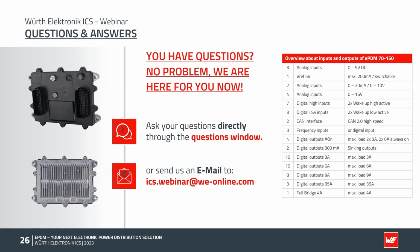Of course, you also have to take into account how long this inrush is happening on the device. So this is a parameter which we have to figure out, depending if it's a lamp, they normally have quite a high inrush, or if it's just the starting of a motor. Of course, you can always, if your load accepts it, use PWM start to reduce the inrush of the vehicles.